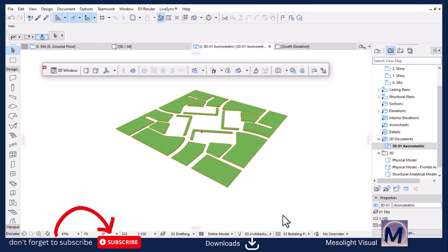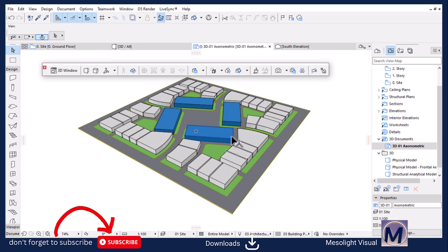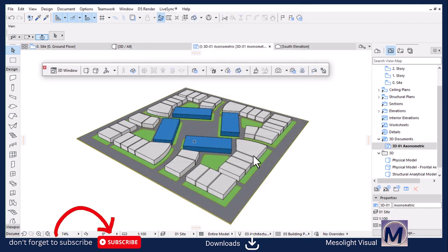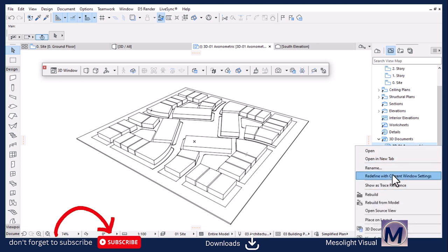It's important, guys, again, to understand the ruling of layer systems and layer combinations. So this is what we have, guys, as the starter. It's nothing interesting yet. We need to define that. So let's see if we change the graphic override to a simplified plane to make all this white, and then I'll right click on the name of the 3D document so that I can go to its 3D document settings.